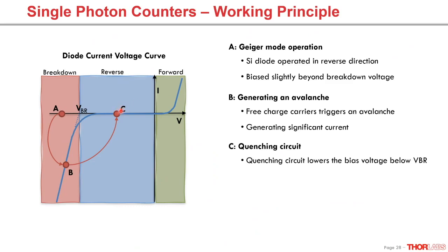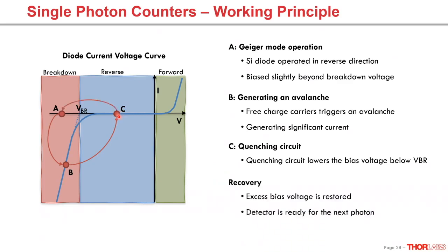During this quenching time, which is known as dead time or recovery time of the diodes, the APD is insensitive to any other incoming photons. After the dead time is over, the APD is loaded again and ready for the next photon.